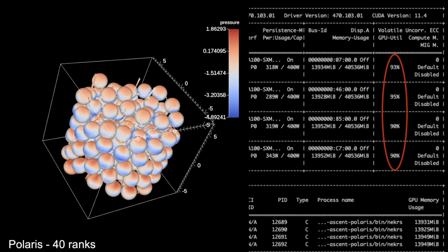Okay, thank you. That's perfect. Coming back to your original question, the example that we're seeing here, the NekRS, it's also CFD. The data lives in its own internal representation, but we converted it to unstructured grid in order to visualize it with a tool like this. So sometimes you need to convert the mesh and the data into a format that the tools understand, or sometimes it will be native. We don't need to run VTK's UI, we just run VTK-m as a library. So it's all in situ, like you're saying. Right, yes. Correct.